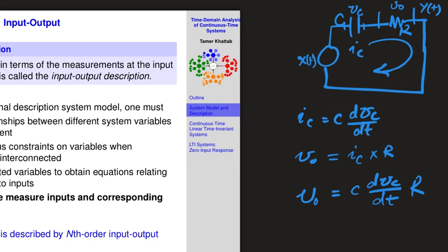Okay, so the sum of the voltages across, that's another step that you have to do, right? So one step was figuring out what happens at every element. The other step is like Kirchhoff's law, for example, the sum of the voltages across the whole loop, or the sum of the currents. So you apply one of those according to your situation, if you are dealing with a node or a loop. So there are two things that help you achieve this analysis: number one, the relation between the signals at every single component, and then some constraint or collective relation when you interconnect components together, right?